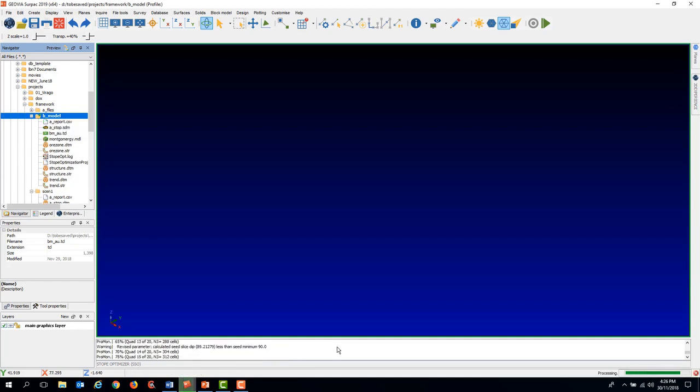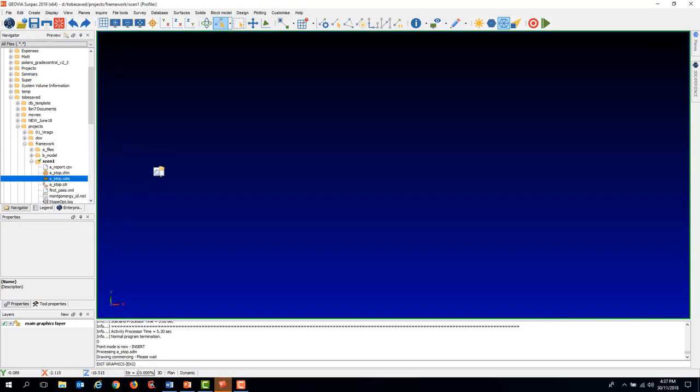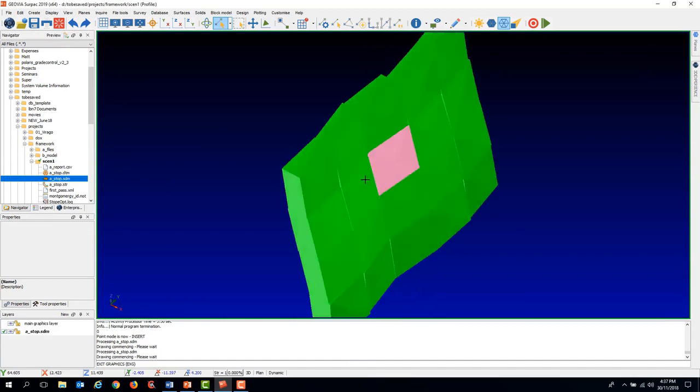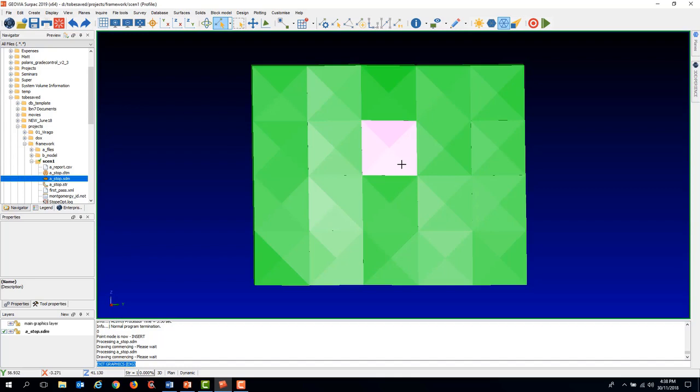This will only take a few seconds because it's a fairly small data set. So we'll go and have a look at the output, and it's in this particular folder. There's my project file. The output is a new file format, an SDM file format, and we'll see what that looks like. So we can see for this load the individual stope shapes that have been generated. They're the 20 by 20 metre full shapes.